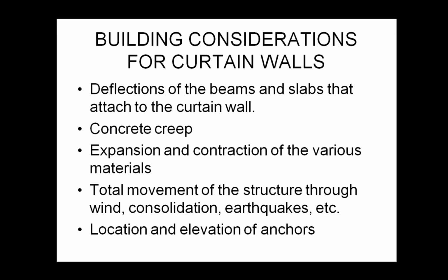All right. So when you're building or designing for that curtain wall, you're always looking for deflections, to make sure that your design is not going to create a tension zone there at the edge where you're connecting to the curtain wall. You want to make sure that those connections are fairly rigid at the exteriors, so that there's not a lot of bend over there. Things that could loosen up, extra pressures, extra tension, are things you don't want in a connection with an exterior portion.